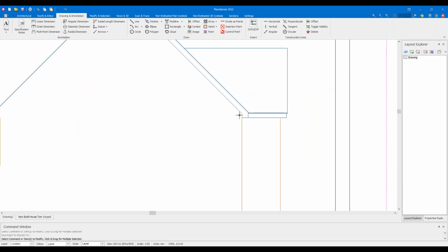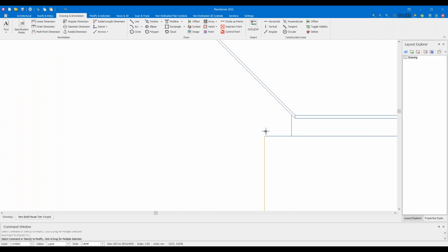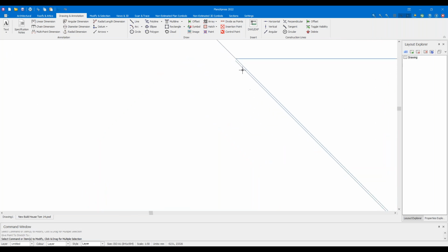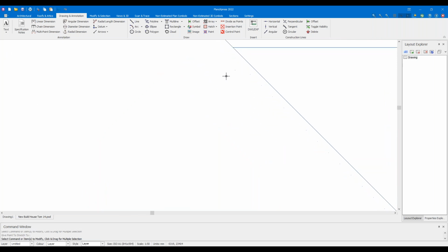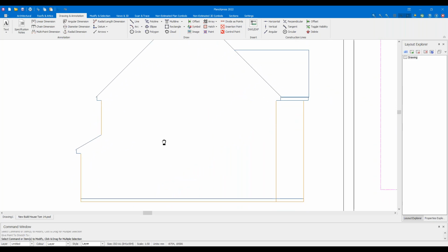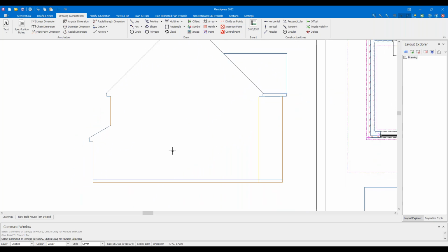Sometimes when you have a semi-detached building and on one side you need to give the indication of what the hatching is being done, well, by say where the building comes together, you can, once you've got an outline of it, and say let's say it's semi-detached right now. Go hatch. There you go, 125 pitch should do, 45-degree angle.